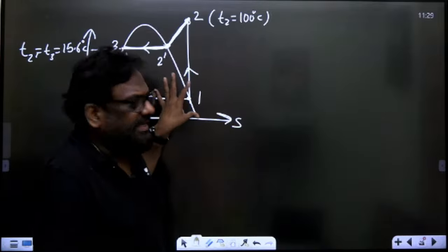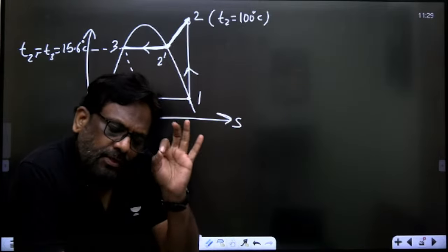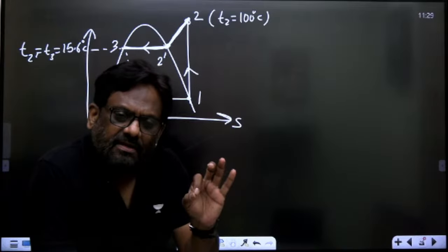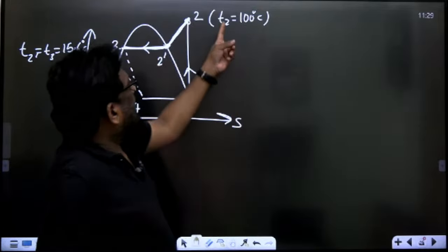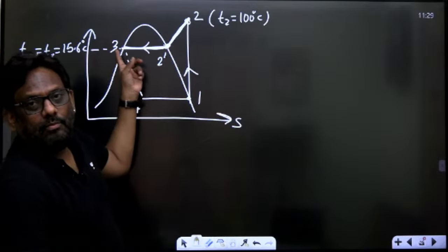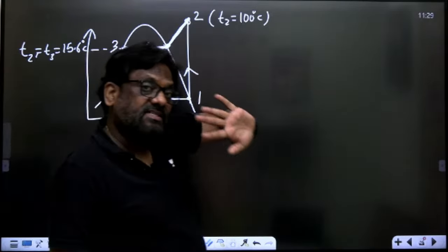But in RAC, in vapor compression refrigeration cycle, the pressures are not that high, therefore you can use the ideal gas equation. Is it understood by everyone, sir? So no problem at all, because temperature is high, pressures are low. That's why I can use the ideal gas equation in the VC cycle, but in the Rankine cycle don't make these mistakes, sir.